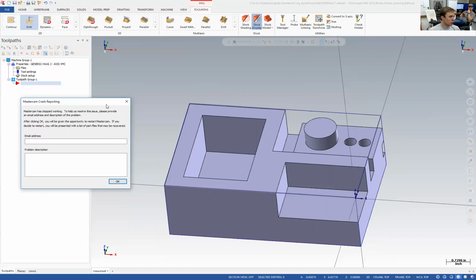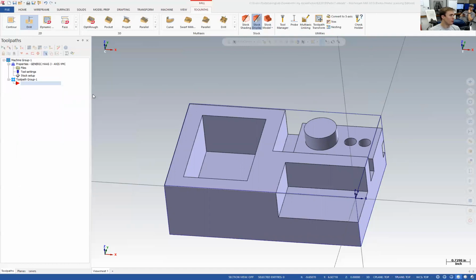Again, like I mentioned earlier, if you are in the middle of a toolpath and you're like, you know what, I should really use a different tool for this, you can go into your tool manager and add it, or you can just create a new tool directly in your toolpath parameters. So it's not the end of the day if you don't get every single tool into your tool manager up front, but it is helpful to help you mentally step through what you want to do with your part before you start doing it.